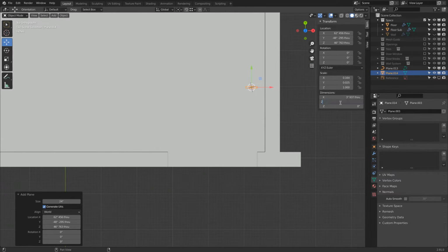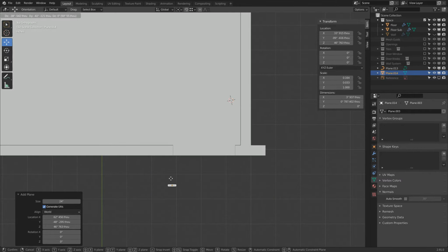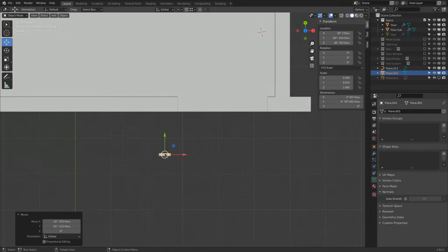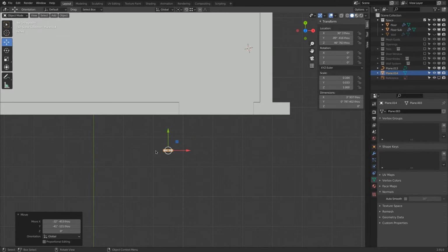Okay, let's say 2 centimeters, just for reference. Move this one to here. Very good. So this is kind of our different version of a baseboard. In one video, I showed how we can create this baseboard with a profile using a polygon approach, and then we put a curve in. Let's build this whole thing via curves, and then we will run it across the spline we created.